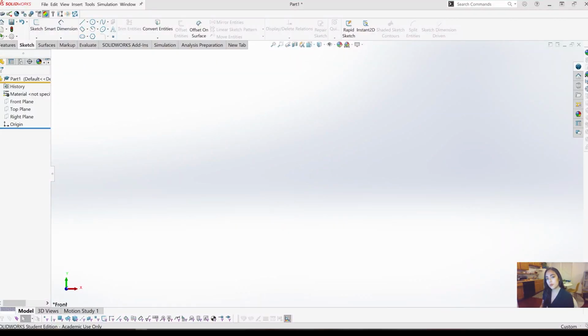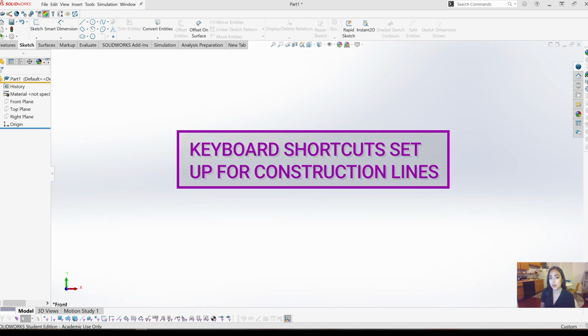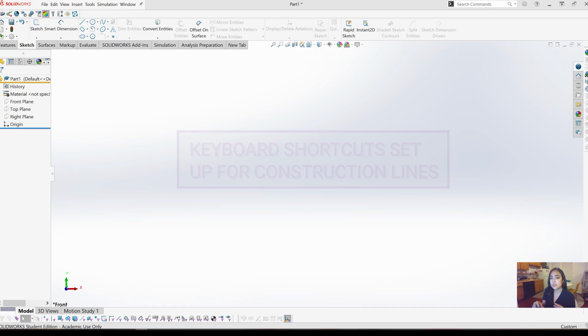All right, let's go. When we start a sketch, we're going to want to make sure we have the right settings for our construction geometry. Again, construction geometry, those are the dashed lines that you use to help design out your sketch, but isn't actually part of the enclosed profile. They're like little helper lines you can use to create references, dimensions, etc.